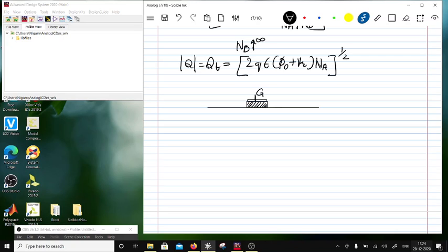So once you have a gate terminal, then what you do is you can implant. The wafer to start with is P minus, right? So now you can implant regions around the gate, and the channel would be formed by the gate itself. So this kind of process is known as a self-aligned process.